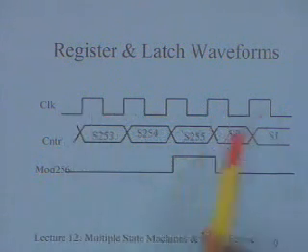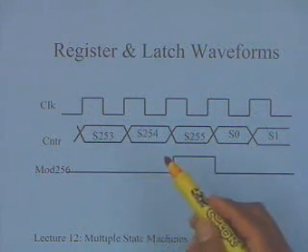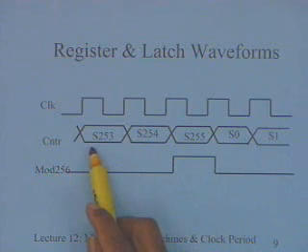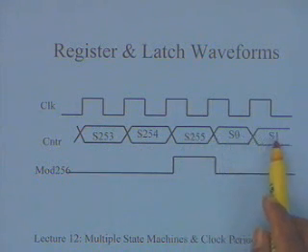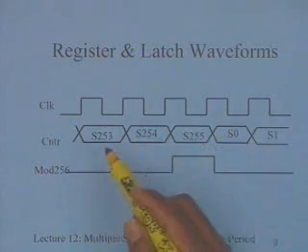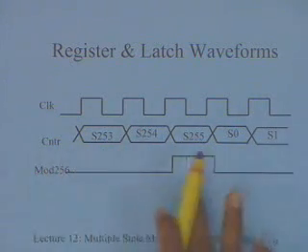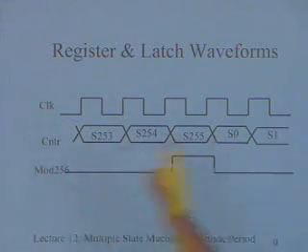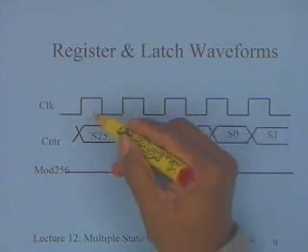So I have this particular clock, and this is a free running counter, so it's going to some S253 state, S254 state, S255, S0, S1. It will keep on going like this. This is not something which is going to stop. Of course, initially it should get synchronized with the first bit that is coming in. That part is still there, but we are assuming that at power on everything is synchronized. So now this particular state transition